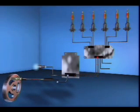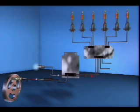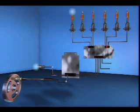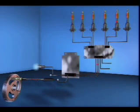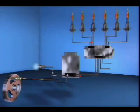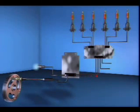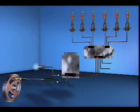After receiving the spark reference signal from the ECM, the ICM fires the spark plug for cylinder number 1, then the next spark plug in the correct firing order each time it receives a spark timing signal. After firing all plugs, the ECM sends another spark reference signal to start the sequence over. Although engine timing is controlled by the ECM, the ICM keeps track of the firing order and fires each plug in the correct sequence.